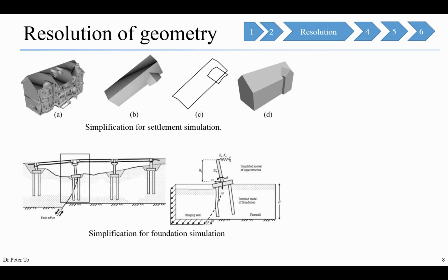In the fifth step, we need to consider the mesh density. Sometimes we do not really know if the coarse mesh is better than the fine mesh or not. The coarse mesh will save a lot of computational time, but it sometimes makes a typical error because the mesh is too coarse, so it cannot simulate tiny reactions or deformation. And sometimes the fine mesh is more than enough. We don't need that detail, and the fine mesh just adds to the burden of the computation.